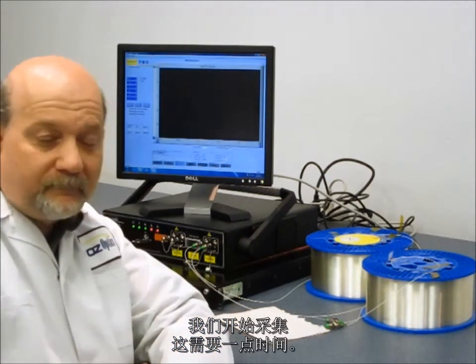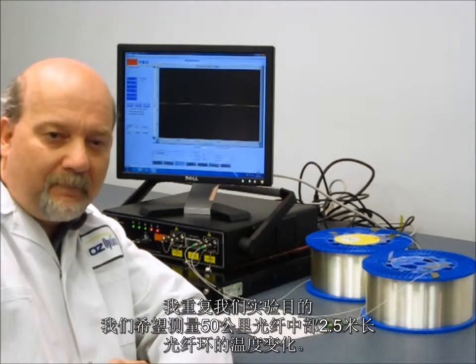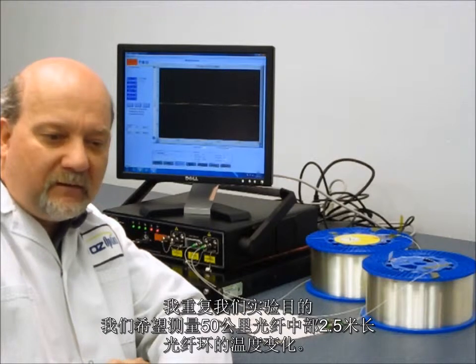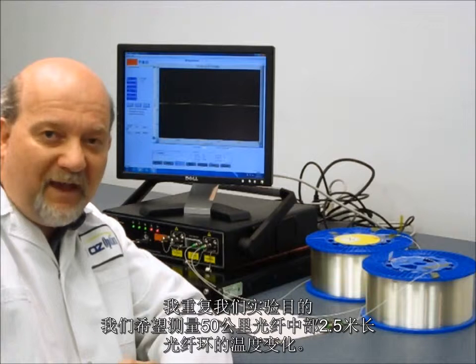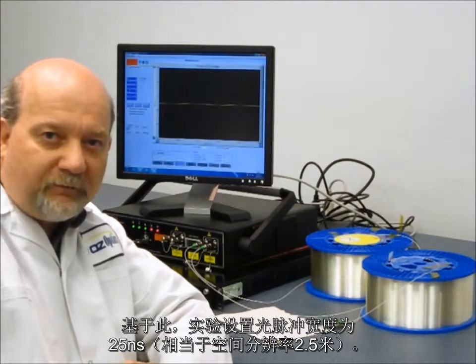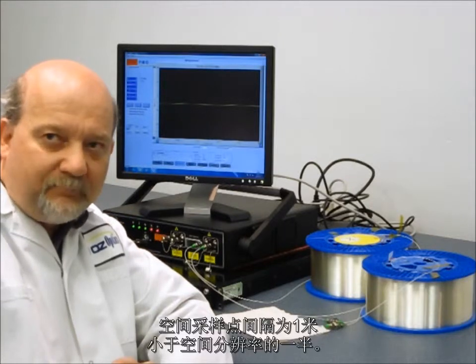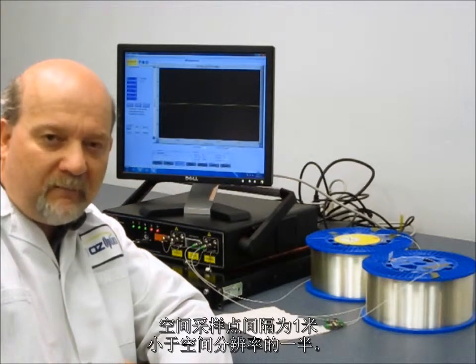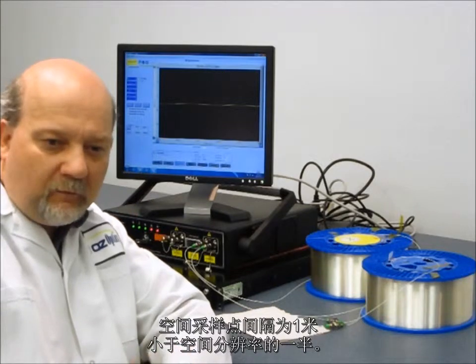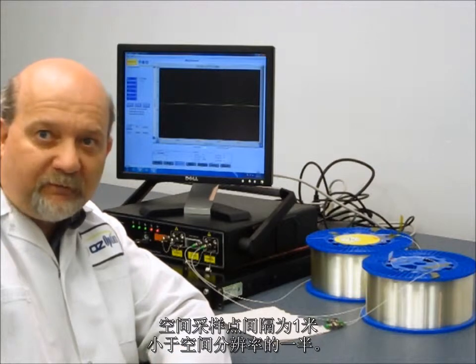We start our recording. Now this will take a while. We're working with 50 kilometers of fiber, and we want to demonstrate the ability to detect changes in temperature over only a 2.5 meter section of fiber. So we have the instrument set up with a 25 nanosecond pulse width, where the pulse is actually going down through the fiber. The spatial steps that we've chosen is 1 meter. Okay? So it's less than half of the section covered by the pulse width.